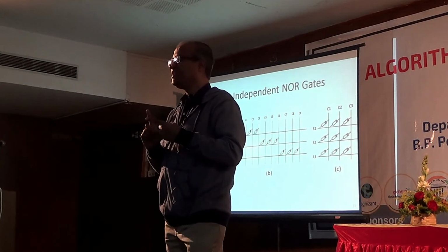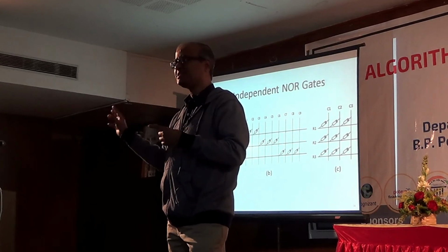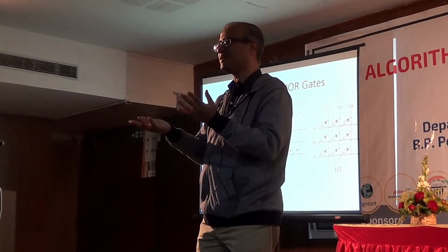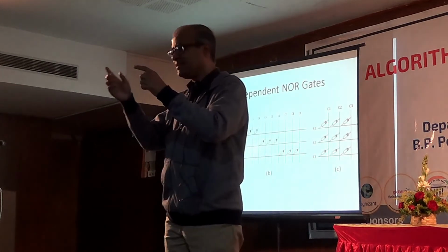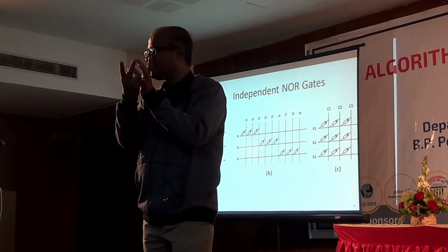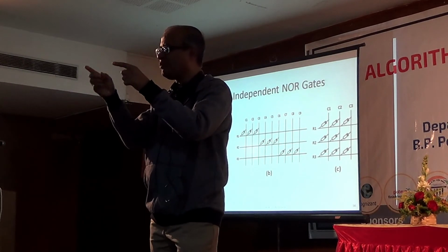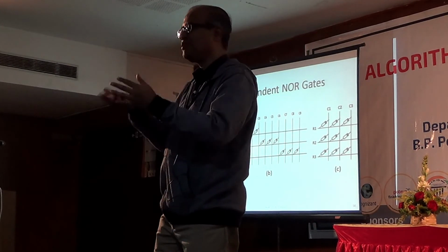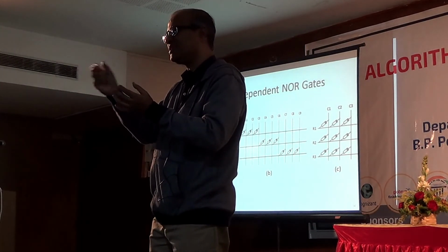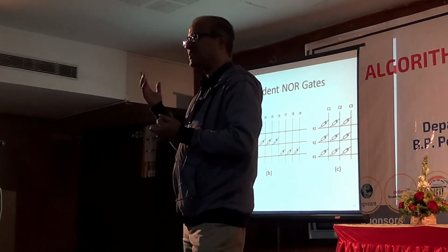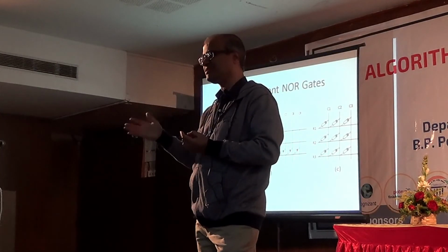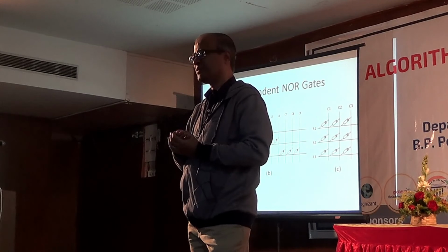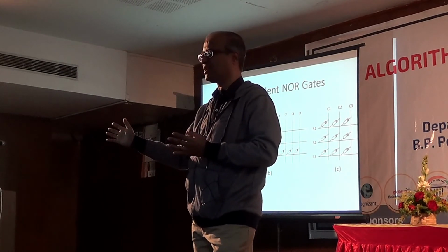One is neuromorphic computing. Memristors can very efficiently implement neural networks, because just by adjusting the value of the memristor resistance, by applying a suitable voltage, you can change the resistance. So for a neural network, for a threshold gate, you can change the weights. There is a lot of work going on where people are seriously trying to build models of the brain using memristor networks. So this is one area where people are actively working on neuromorphic computing.